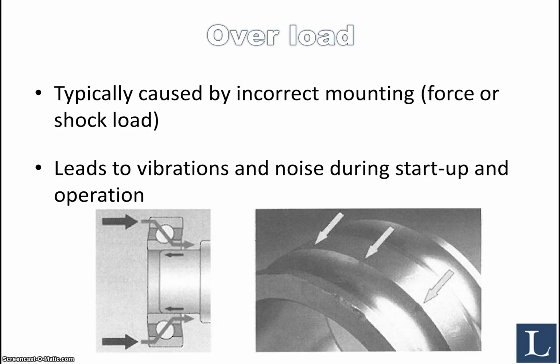Overload typically is caused by incorrect mounting. You use excessive force or shock loading to the bearing, and obviously if the bearing is damaged, the races are damaged and so on, this will lead to vibrations, noise during startup and during operation, and your bearing will not function as intended, and you will probably encounter early failure also because you have stress concentrations in different parts of the bearing.